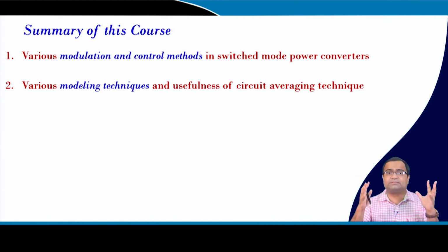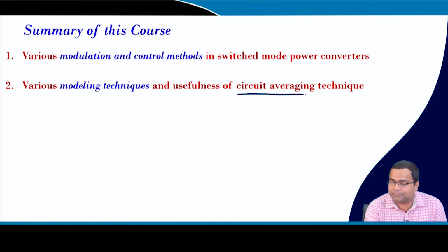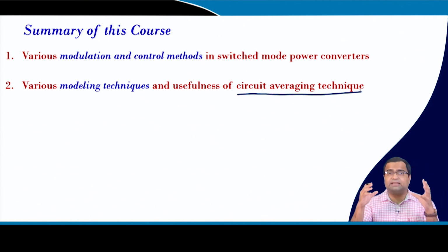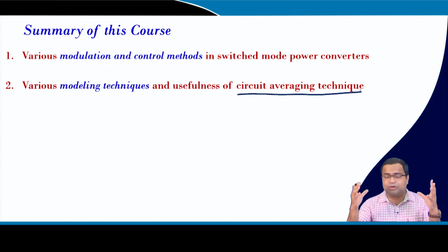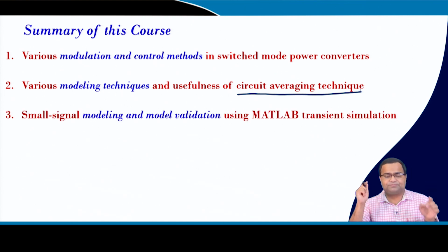We have emphasized small signal models using the circuit averaging technique, and one important point that I want to highlight is that this technique gives us physical insight, because we have often talked about input impedance, output impedance, audio susceptibility, and the control to output transfer function. So, if you want to understand from the circuit point of view how to shape the response, the circuit averaging technique as well as the equivalent circuit concept was very important.